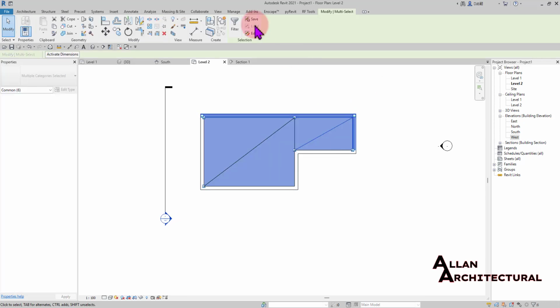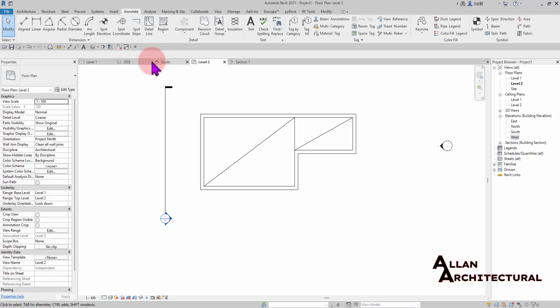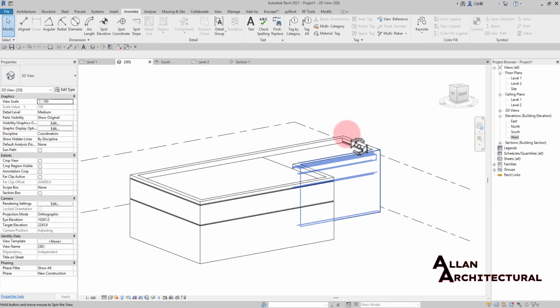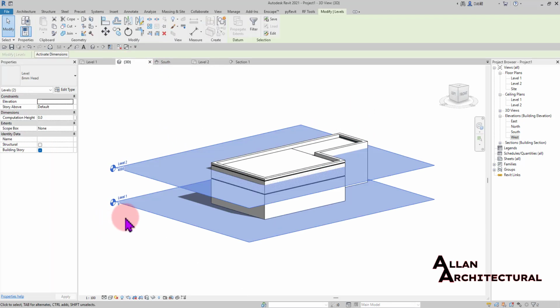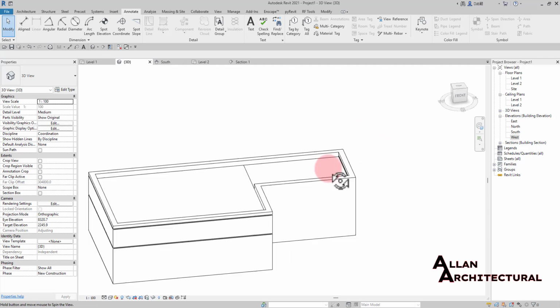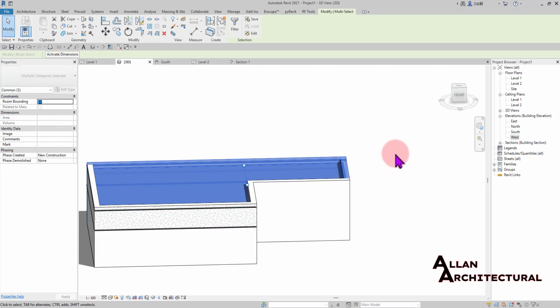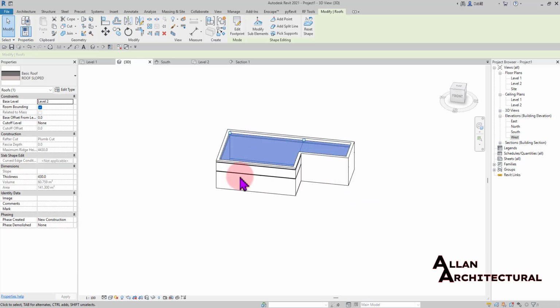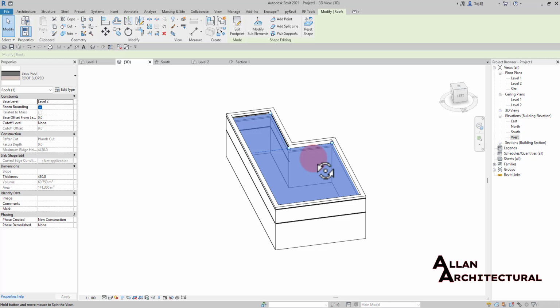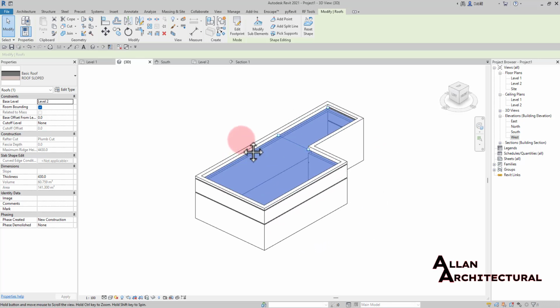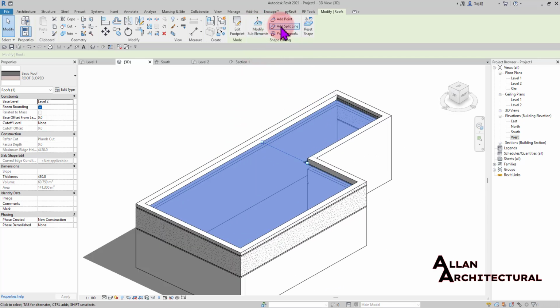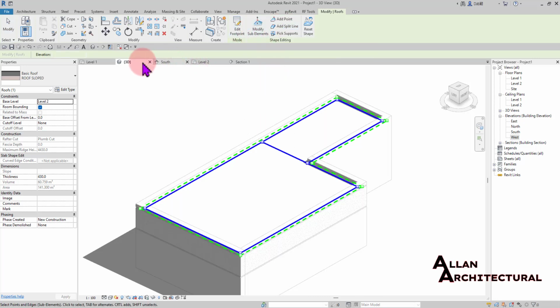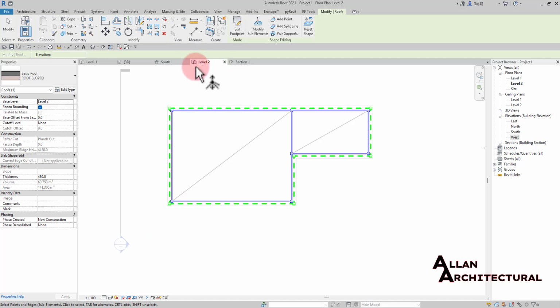And when we select everything in our roof, let me head into the 3D view. All right, so I'm just going to hide all these level lines, EH on your keyboard. When you select all of those roofs, you're going to notice nothing really happens in our roof. That is because we haven't added our points in there. So now when you select that roof, we go into our modify sub elements, and then we are going to head into sub level 2.